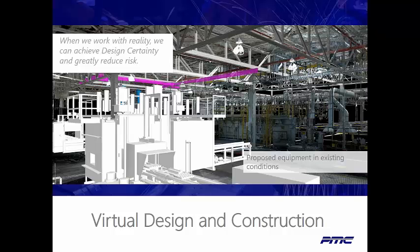In 2012, a large automotive manufacturer needed to install the fifth in a series of identical heat treat furnaces. For the 4 previous installations, the decision was made to remove the roof and raise the bottom truss cord by 10 feet. When production needs drove the decision to install the fifth furnace, plans began to raise the roof line once again. PMC was able to scan and work with a structural engineer to design a plan that eliminated the need to raise the roof line of the building. The manufacturer's model was inserted into the point cloud to verify clearances.